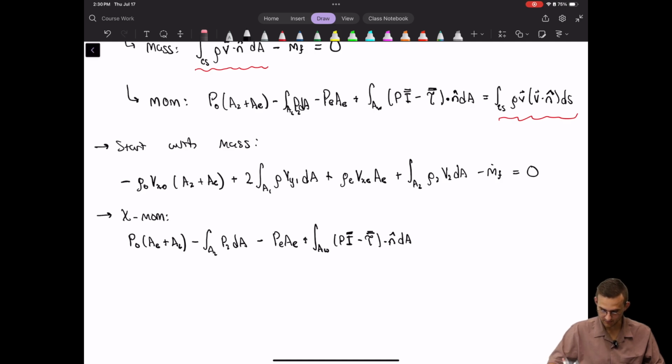And then let's expand what's happening in that integral. The first thing is we have the mass flow rate times the velocity entering the entrance. And like I said, the velocity profiles and all of the properties are uniform, or quasi 1D, at the left-hand side of the diagram.